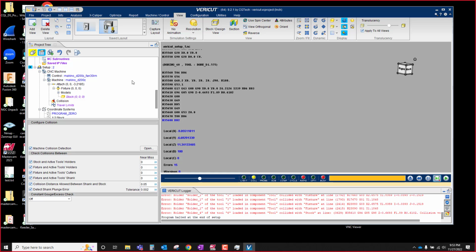Or you could rough a part out to where you've got stock all over. Now you're going to take it out and heat treat it. It's not going to show you the heat treat, but now you're taking your part back from heat treat and loading it in a different mill on a different fixture, and you're doing side 1, or op 10, or whatever it is. Then you're going to remove it from the fixture and load it on a different machine or in a different setup, different fixture, different vise, whatever, and continue the machining process until you're all done.